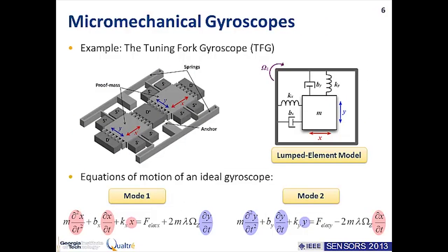So what we usually do in order to get these micro machine devices to operate is we design them to have a particular mass, similar to the pendulum. We have that proof mass swinging back and forth. That can be modeled as a lumped element parameter of two sets of second-order systems. These two systems are one about, in this particular case, the x-axis. So we design this structure to have a particular spring that allows it to move back and forth about the x-axis. And then another system that has compliance about the y-axis.